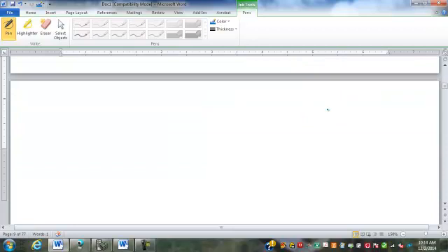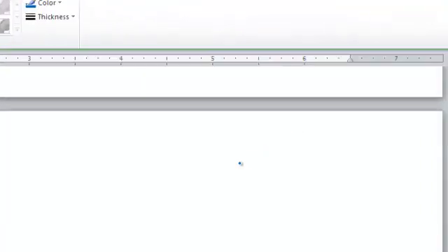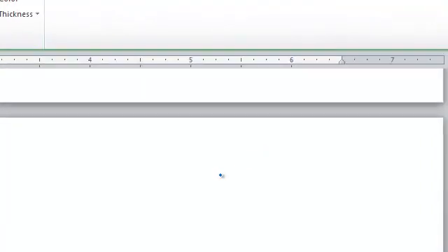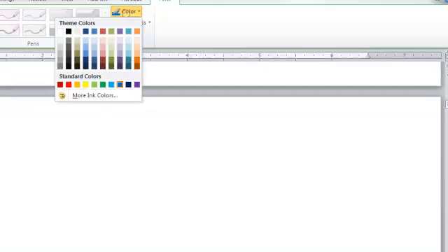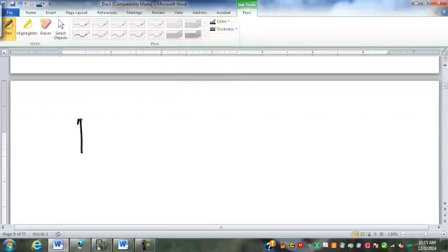how do we then look at a beam and decide how much is going to flex? Well, there are a couple of ways we can go about it. If we have a simply supported beam, and let's say that this has a single point load on a 12-foot span, we'll give it a single point load of, I don't know, 3,000 pounds here.